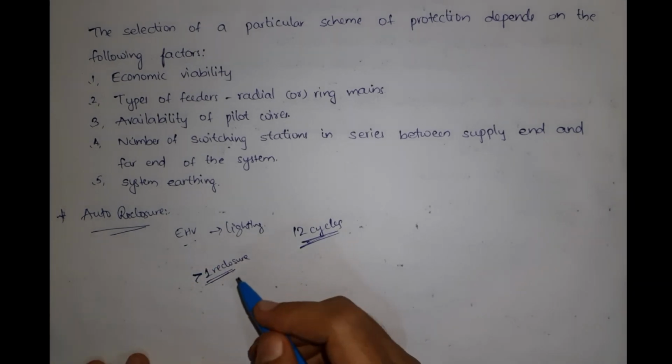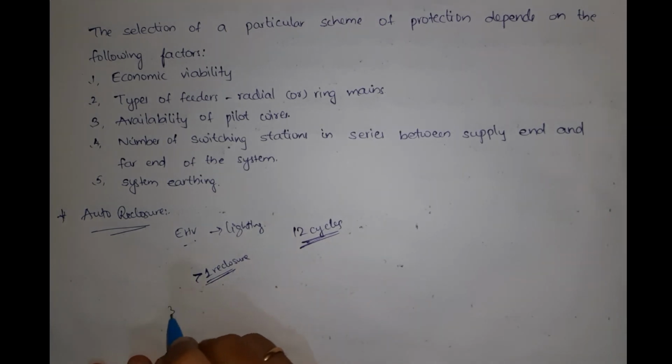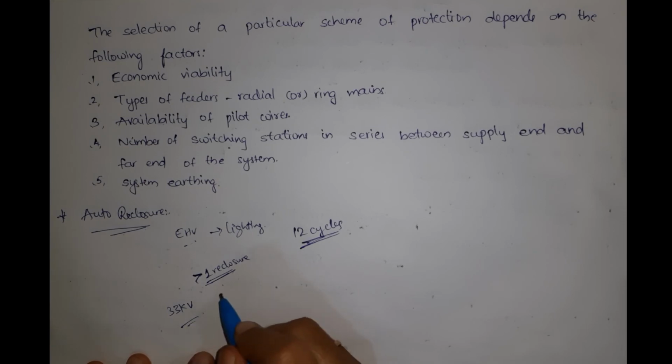On lines up to 33 kV, most faults are caused by external objects such as tree branches and so on. This is due to the low height of poles compared to adjacent trees. The 33 kV lines are generally shorter than the trees, so this affects the stability of the 33 kV system and causes many faults.